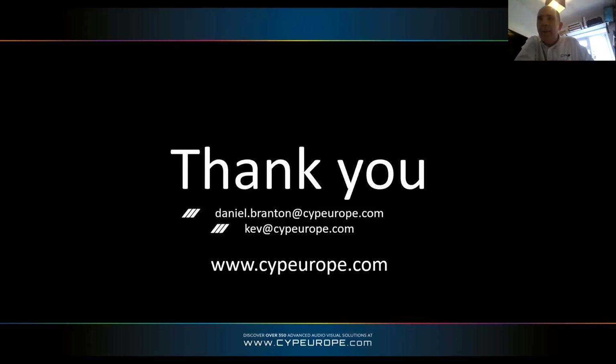What else have we got there? Bjorn, third choice button for auto. No, Bjorn, we've kind of played with this setting. This is about the DHCP auto IP, and the SDVoE system only has two things it's allowed to do. It's only allowed to do static and DHCP. So we've written in this auto IP section to it, because there's no way of us being able to select that as a mode on the actual chip, because you can only address what the chip's allowing you to.